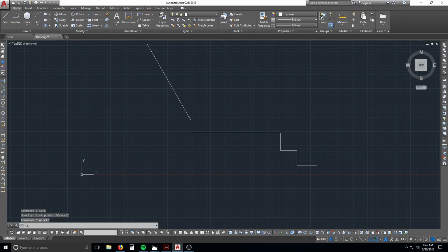however you want to do it, but usually I use space bar. So it's L, enter, or space bar, or return, and then left click again, and then return gets you out of the command. That's going to be pretty universal for everything. That just takes practice. I'm not going to say that comes naturally. Some people it might, but alright, that was rotate.